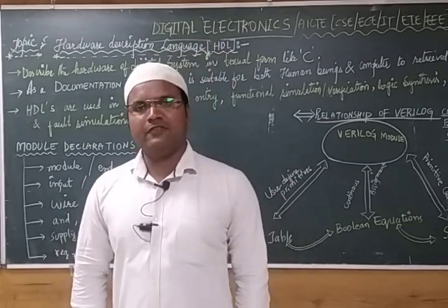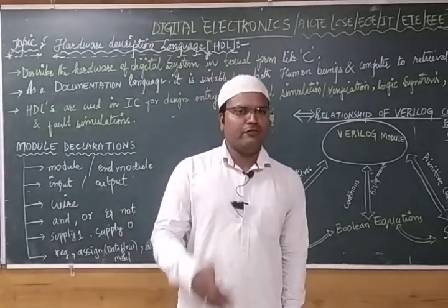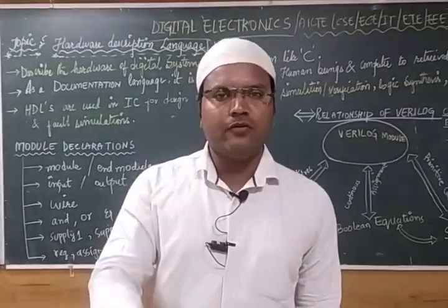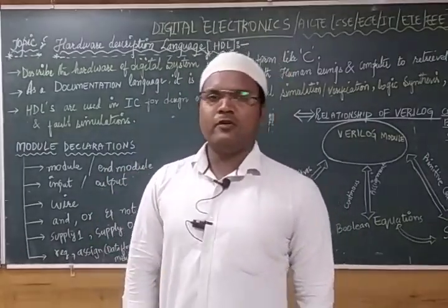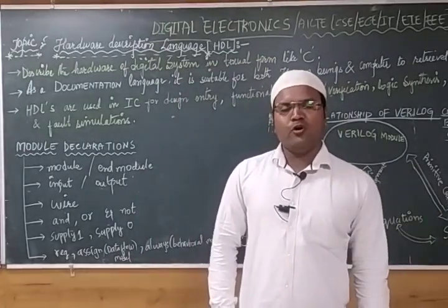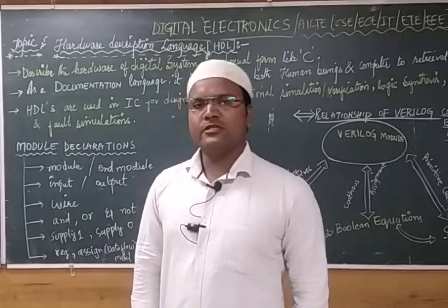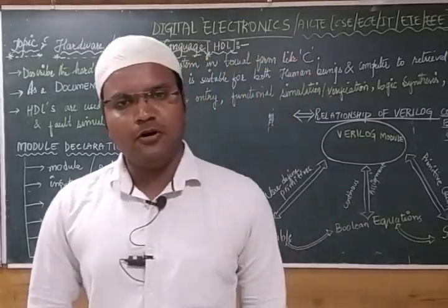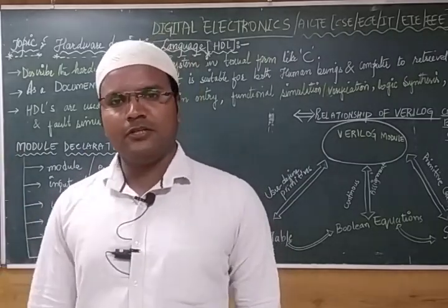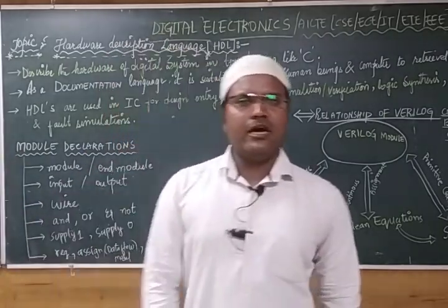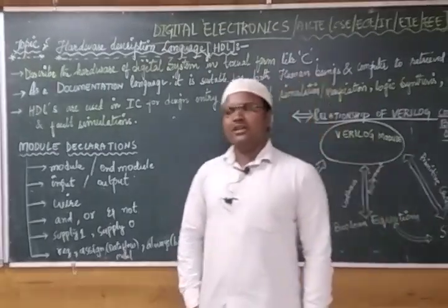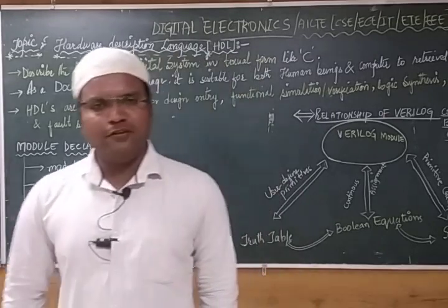In the D flip-flop, we have connected one. The D flip-flop and toggle flip-flop are both unary, where they take only a single bit. What does a single bit mean? It takes only one bit as input, and the outputs are Q and Q bar, right? So the sequential circuit depends upon how we get the present state. If you want the next state, Qn plus 1, we designed that by using the characteristic table. These are all the concepts we discussed in the previous class for the D flip-flop, toggle flip-flop, SR flip-flop and JK flip-flop.